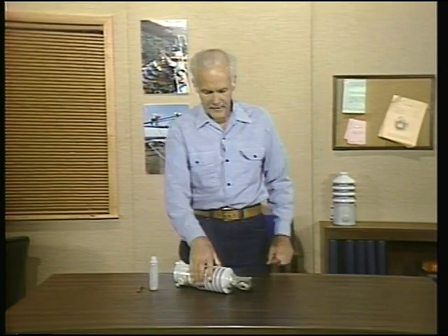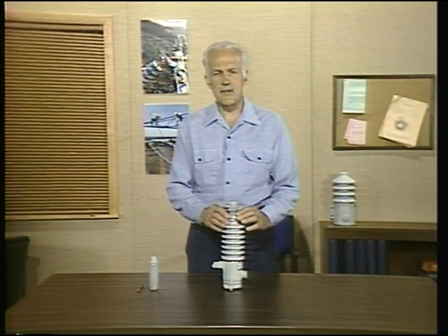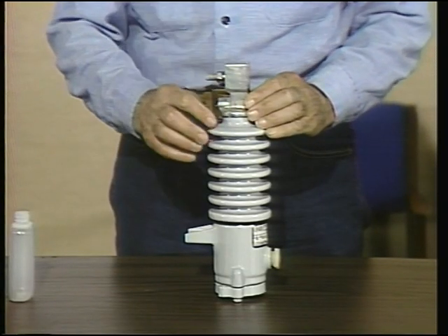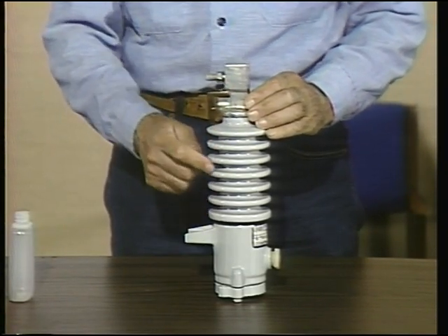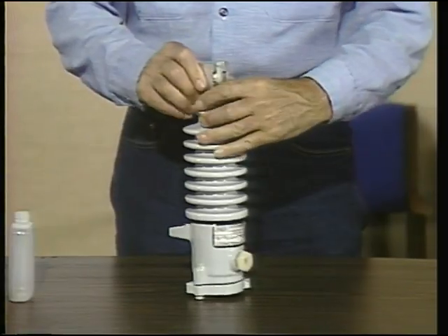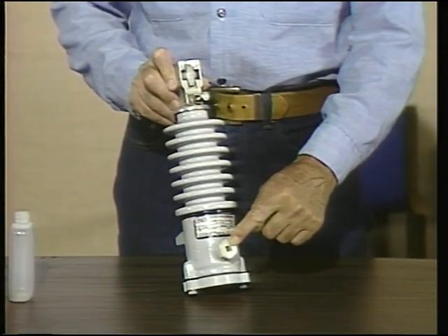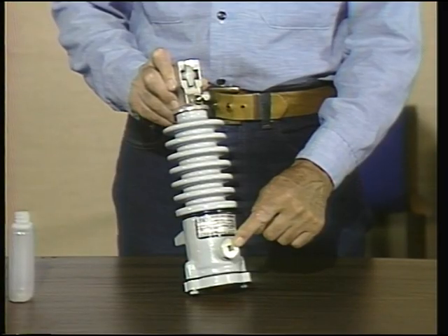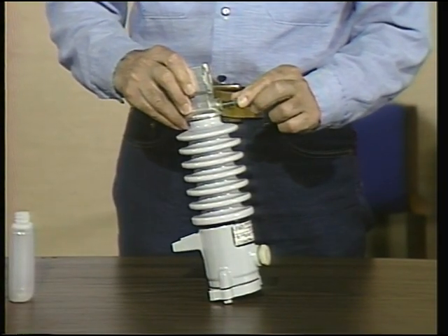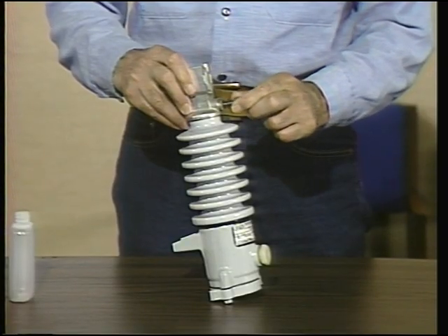First, let's look at the terminator itself. This is a typical porcelain terminator that's filled with an insulating fluid. It has insulator skirts, a mounting bracket, a sealing plug which covers a drainage hole for excess insulating fluid, a set screw and lock nut for tightening down the conductor after it's in place,